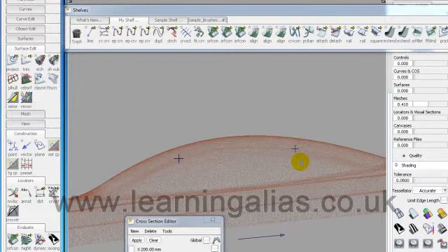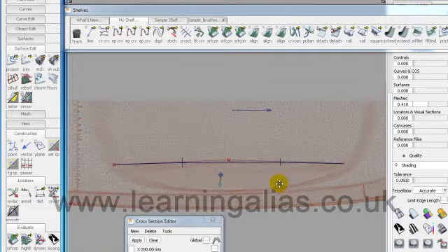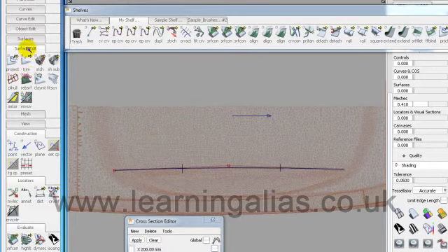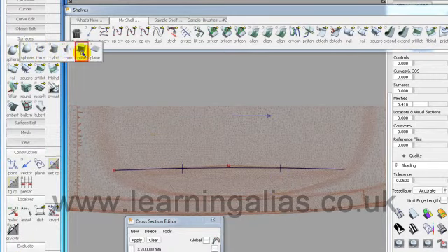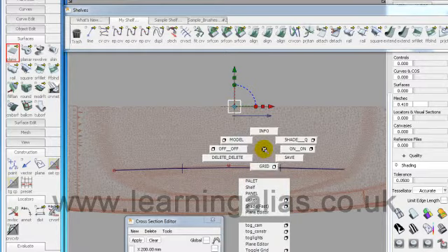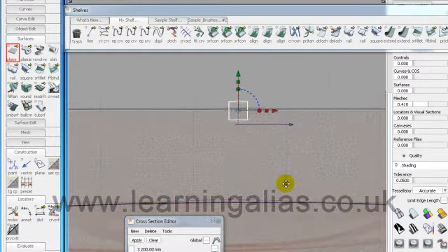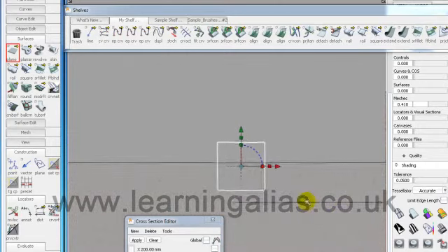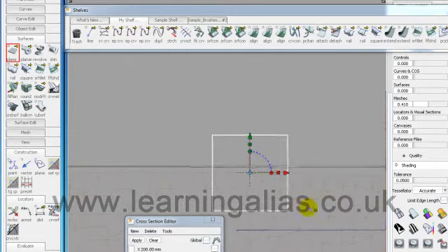I'm going into F5, and without any further ado, come over here and in surfaces get the plane, and you want that plane or surface to be set at degree 3, and then curve snap it to the edge of the mesh. Don't bring it in here, make sure it's at the edge of the mesh on the center line of the car. And then it's quite a good idea at this point to check using the grid that it is actually the center of the car, and as you can see it's a good job we checked because it isn't.